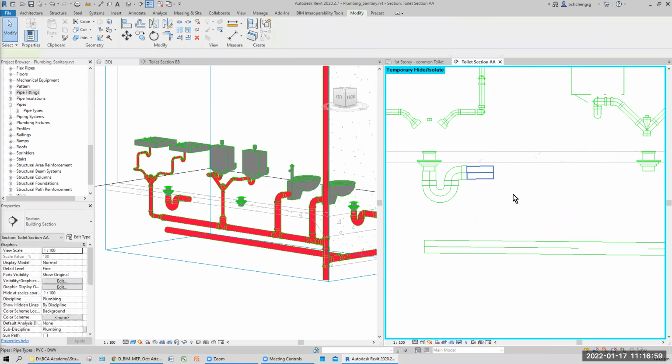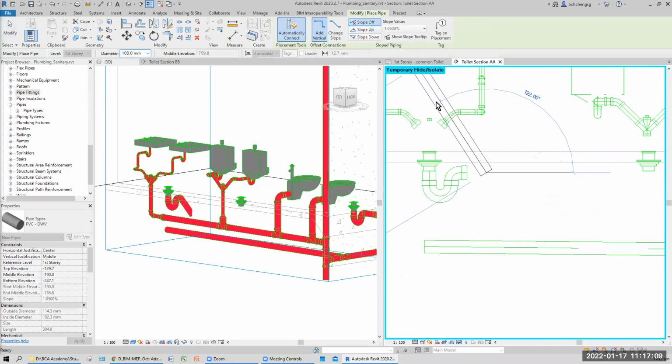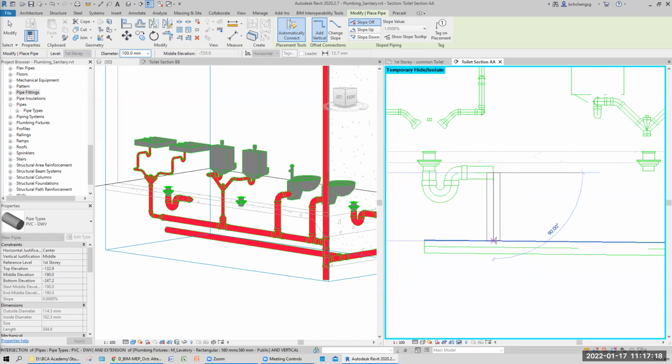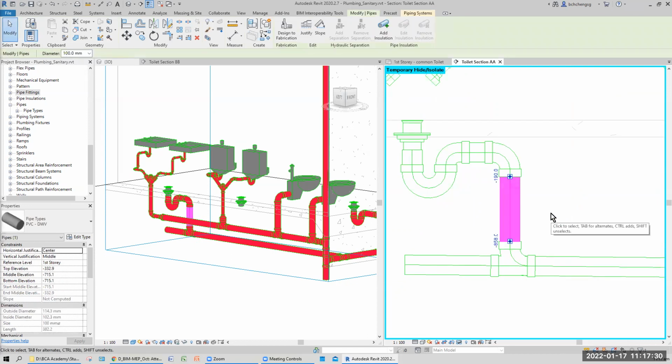This is wrong. Point, right click at the grid, connecting point, draw pipe, it should be slope off. So you draw a straight pipe. See, straight pipe. Then vertically down, touches. Okay, this is correct now. Now, whether you want them far or back to back, you select this and you move it. Okay, like this.